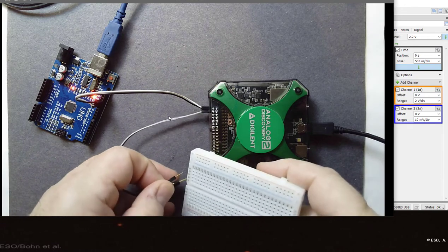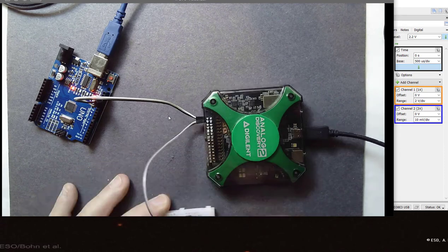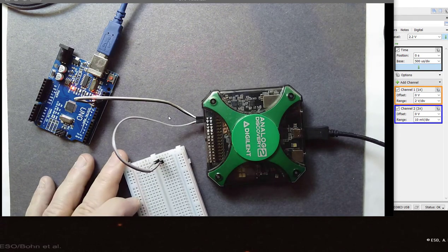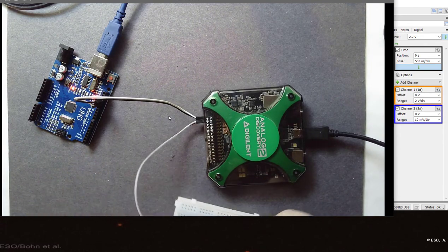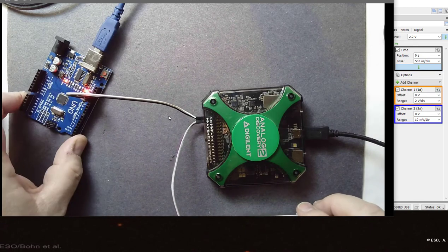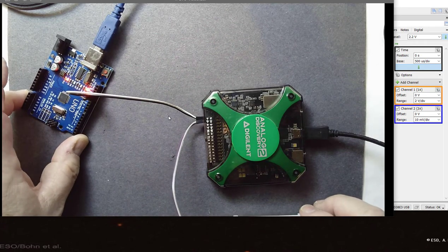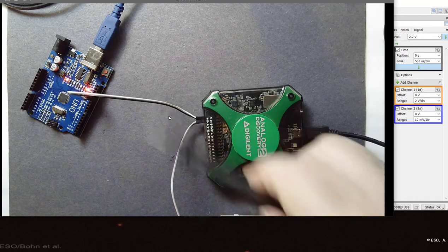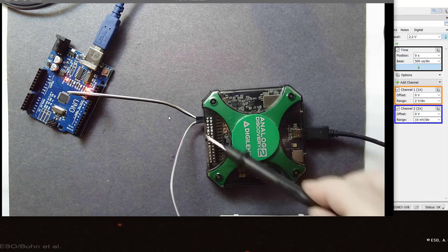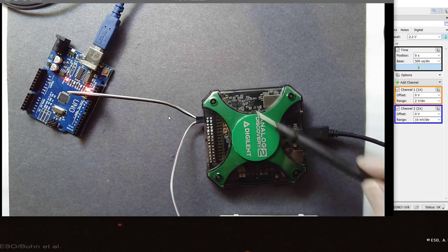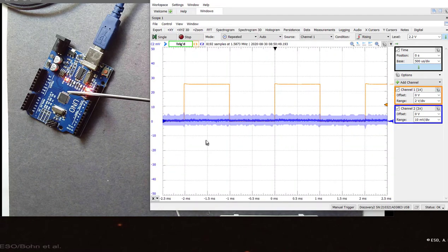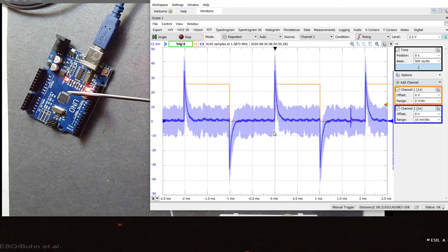So I'm going to short these two leads together. I'm just using the solderless breadboard to make the short, and now I can keep those wires far apart. So I'm going to dramatically reduce the inductive coupling between the aggressor loop and the victim loop, and now we'll look at the crosstalk, the magnetic field crosstalk, the inductive crosstalk inside the 82 scope. Well, you see a dramatic reduction in the capacitive coupling. If I open up the leads, there's the capacitive coupling.